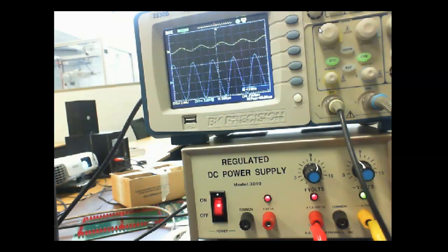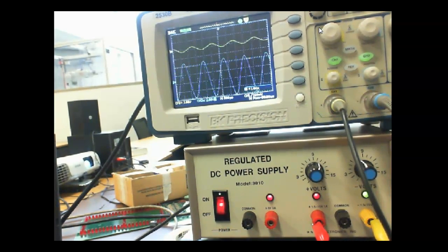But using those capacitors, I can bring AC into it, couple it into DC, make the DC change at an AC rate, right? You understand? My collector, I get AC riding on DC. Then I bring it to a capacitor, and then I get AC out. We call those coupling capacitors because that's what it does. It couples AC in and does what? It couples AC out.